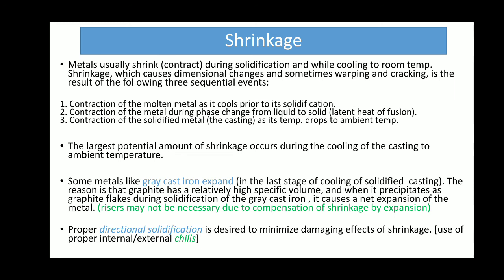Generally, in the third stage, that is during solid cooling or solid contraction time, the main riser consideration comes. But in the case of gray cast iron, whatever contraction happened in the first and second stage, in the third stage it is expanding.